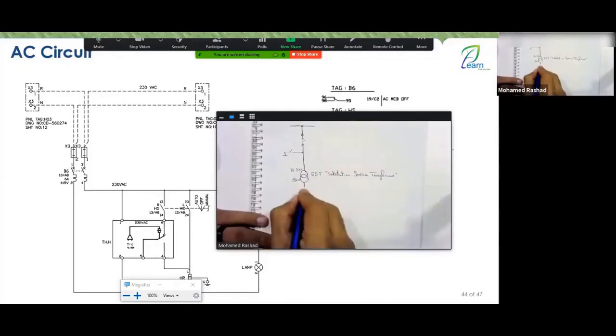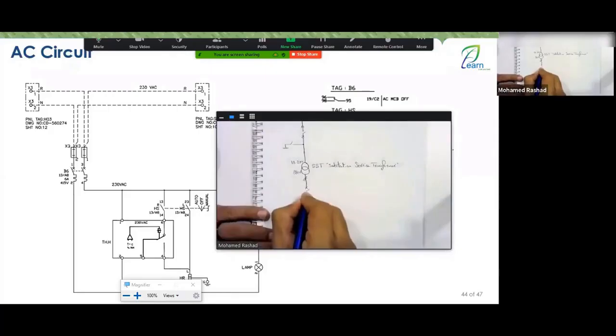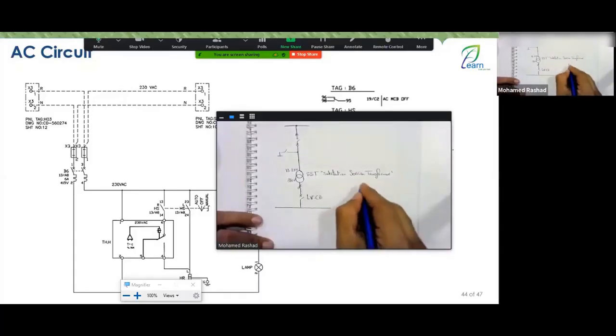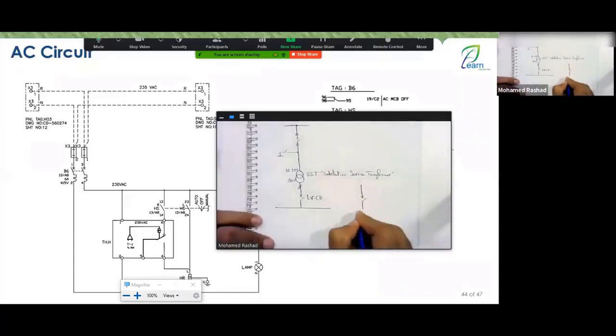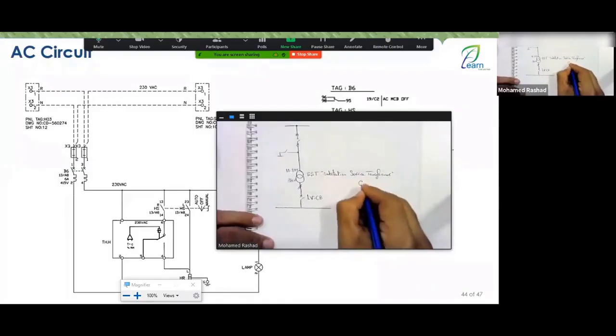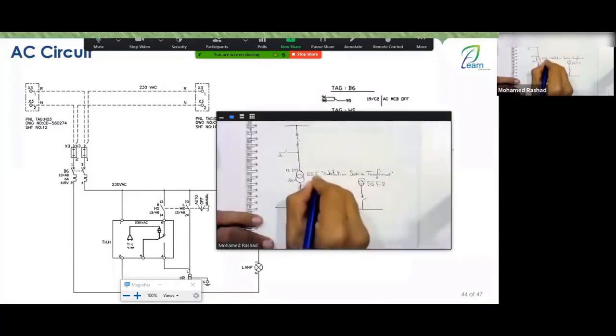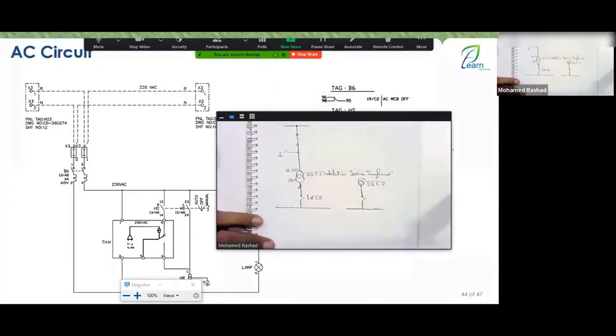You take this 380 volts, which is of course three-phase, and you connect it here to a low voltage circuit breaker. It will be fitted with a breaker, and this is how it becomes an incomer. And what does it connect to? To the bus. You also have another substation service transformer that comes here and also connects to an incomer and then to another bus. So here you have two substation service transformers. For example, this is substation service transformer 2, and this is substation service transformer 1. And between these two, there is also a bus section.